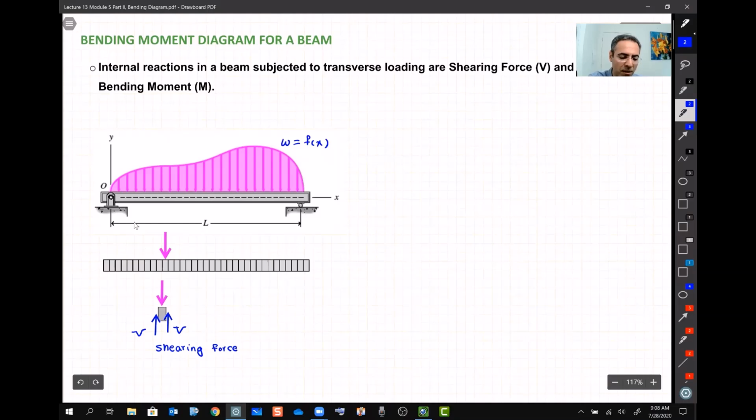And it's very simple. Always imagine this beam as lots of slices like this one. Each load on each slice tries to slide this small element off the rest of the beam, but there is going to be friction between them. Remember the shearing stress that I explained to you? When two things want to slide on top of each other, there is going to be a shearing between them, and we call it shearing force. Therefore, we know that on each cross section of this beam, no matter where I look, there's going to be a shearing force, which we call V.